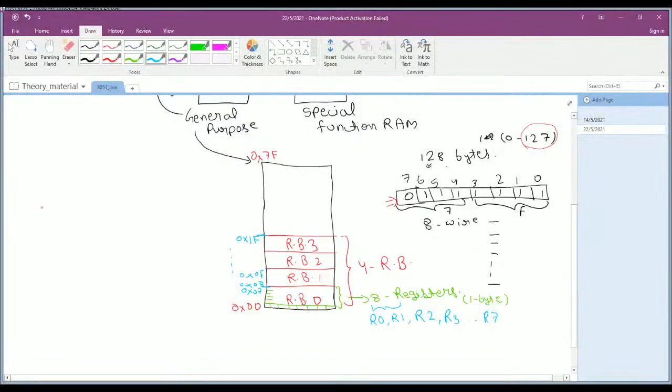And remember our last command, as I wrote register R0 and #15h. That indicates this number 15 is stored into the R0 register. Now you know more about this RAM structure. Now you will come to know which register 0 it goes to, whether of register bank 0, 1, 2 or 3.